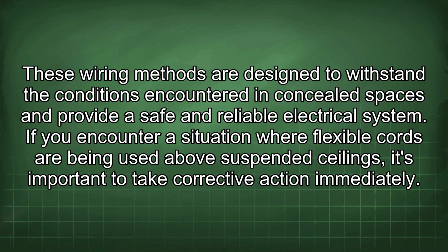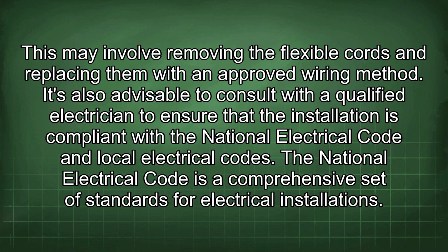If you encounter a situation where flexible cords are being used above suspended ceilings, it's important to take corrective action immediately. This may involve removing the flexible cords and replacing them with an approved wiring method. It's also advisable to consult with a qualified electrician to ensure that the installation is compliant with the National Electrical Code and local electrical codes.